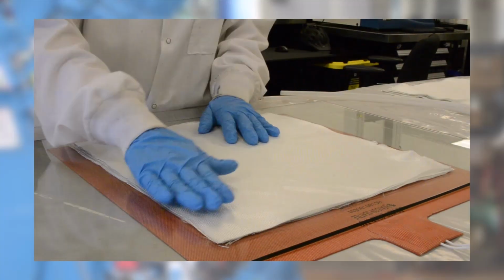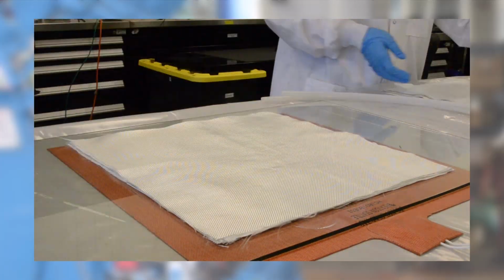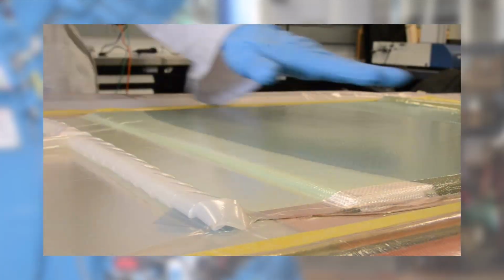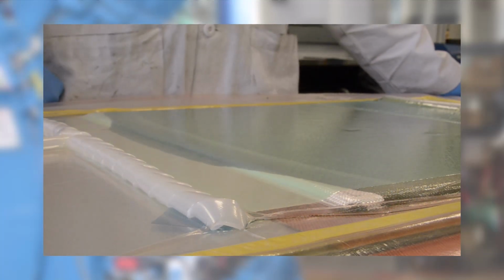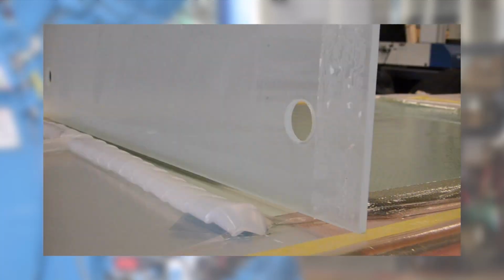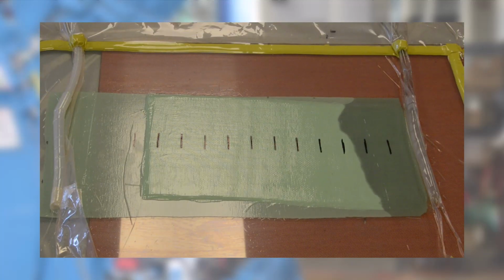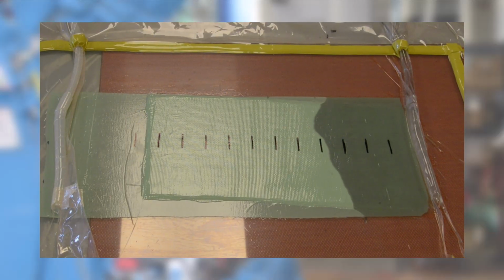The room temperature affects the temperature of the resin, hence the viscosity of the resin somewhat depends on the ambient room temperature. Vacuum infusions conducted during the winter versus in the summer can have wildly different results. It is important to account for these temperature differences. A heating pad could be placed along the outside of the vacuum bag, so that a constant temperature can be maintained during the vacuum infusion.